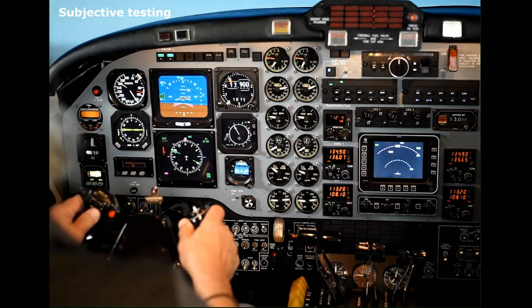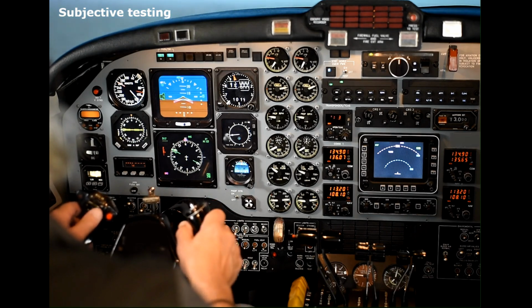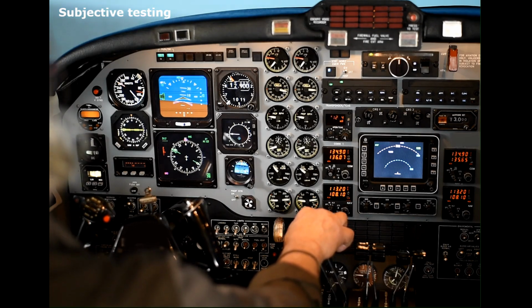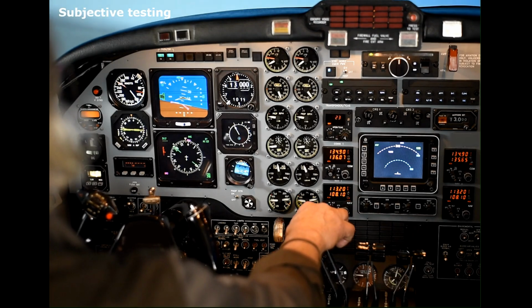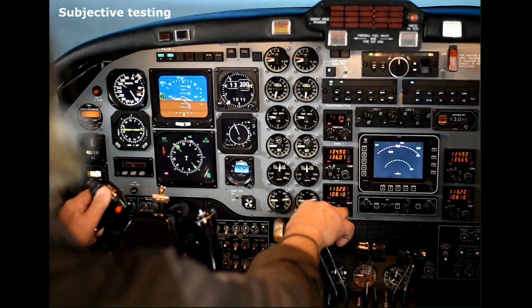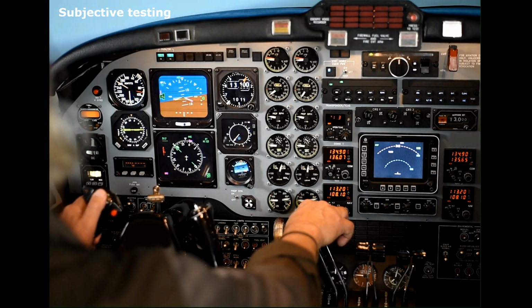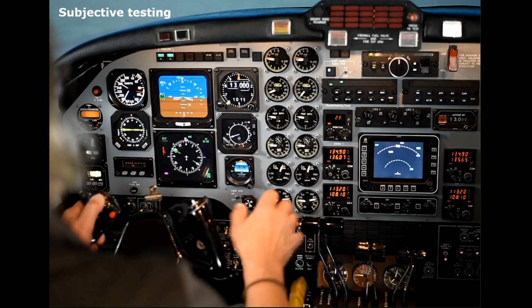Going back to 13,000. Less pull needed on the yoke for the bank, as it should be. As in trim, increasing power. Hands off. As the speed increases, aircraft keeps climbing, and trim needed. Back to the original heading. Everything feels as it should be.